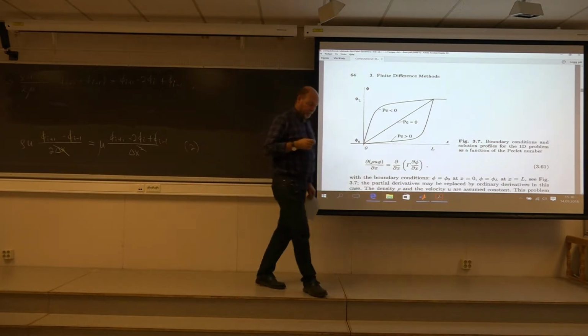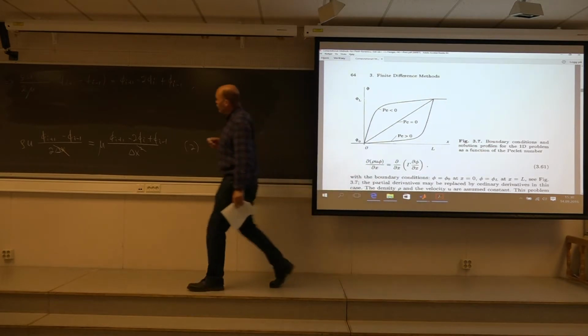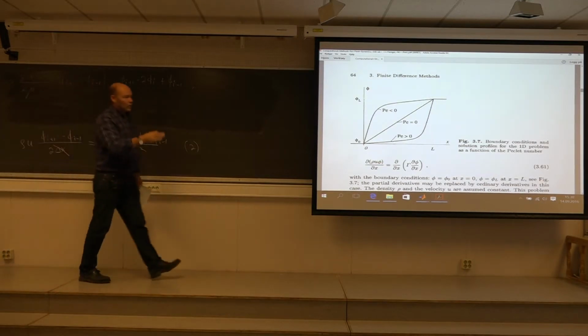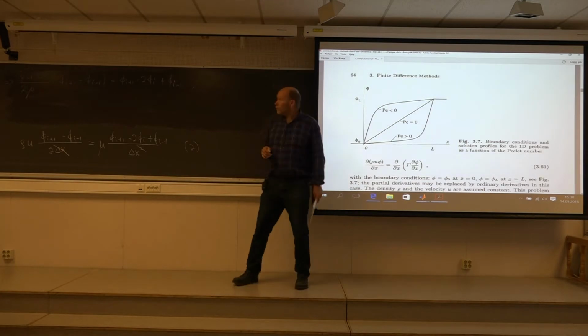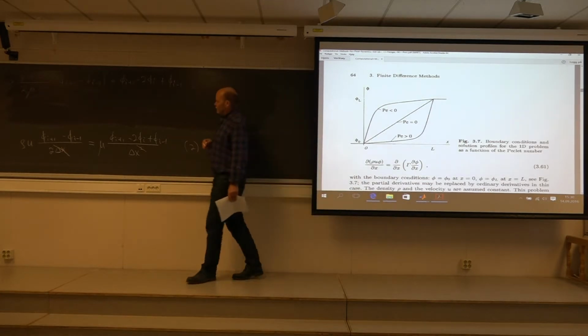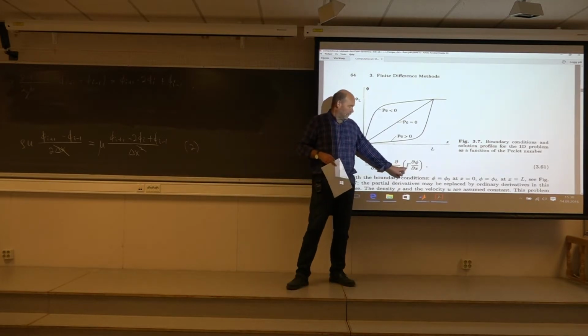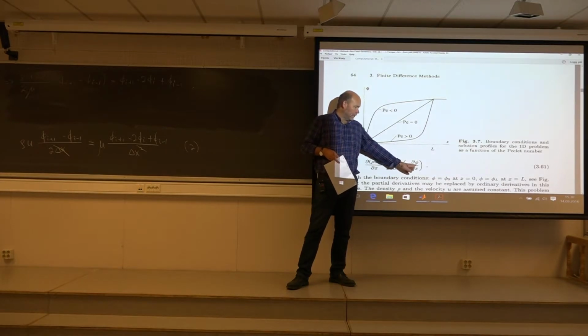Then we baptize this quantity here. This is something you should recognize. You have a density, you have a velocity, and you have a length scale divided by the viscosity. This is a Reynolds number. In the book here they call it a Peclet number because in general, this large gamma, a sort of diffusive coefficient, can be anything depending on what this quantity is.